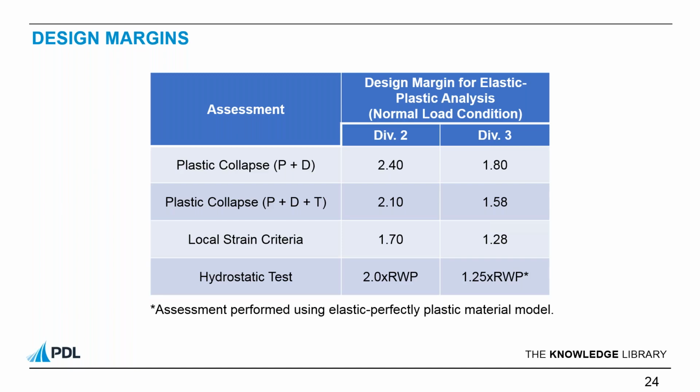The first is only applicable to materials below 80 KSI, I think. The second method is applicable to all materials, but it's essentially a means of looking at your loading regime and counting the number of cycles in which you're going to exceed certain load levels and comparing that to certain limits within the code. Okay, no, that's great.